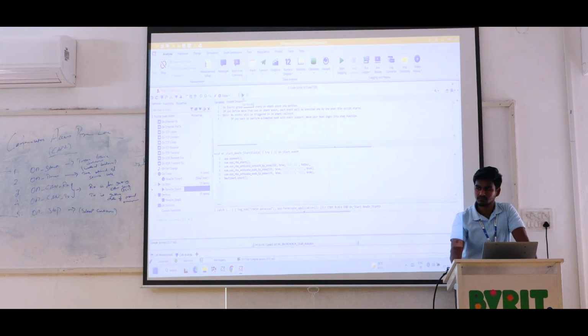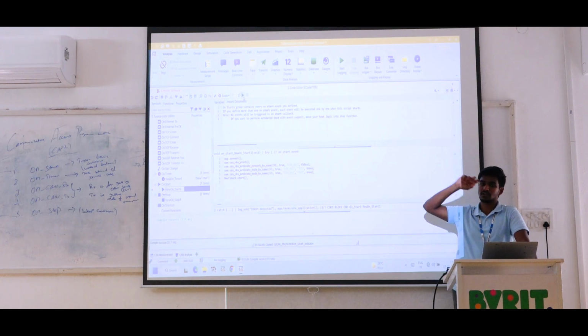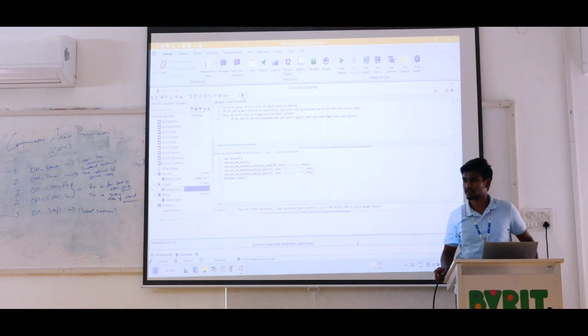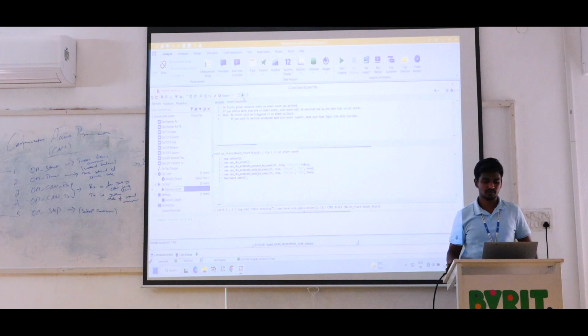Directly we will need to stop the channel itself, otherwise the remaining things will be on. So that's why we want to specifically turn off everything. Yes. Now we just turn off the RBS, it will again turn on, it will be 0, but the nodes will be in activating mode. So based on that the bus load will decrease. Okay.